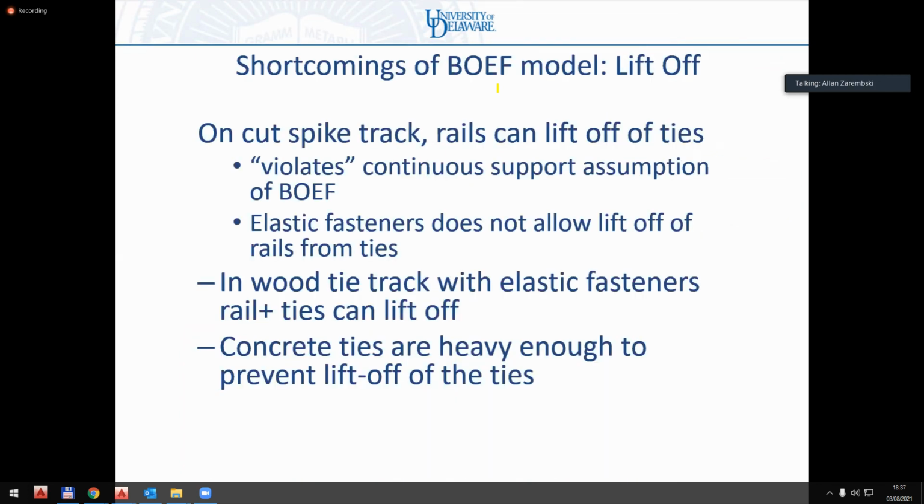Now, the beam on elastic foundation model, like all models, has some shortcomings. One of the first ones is the liftoff. When we have a deflection curve, there's an uplift. You don't get much uplift off of the concrete sleepers because they are heavy enough to keep it down.